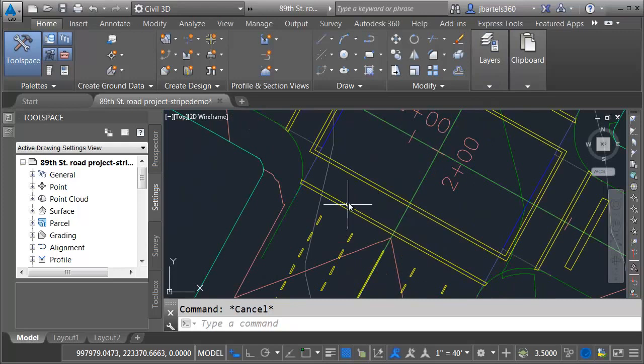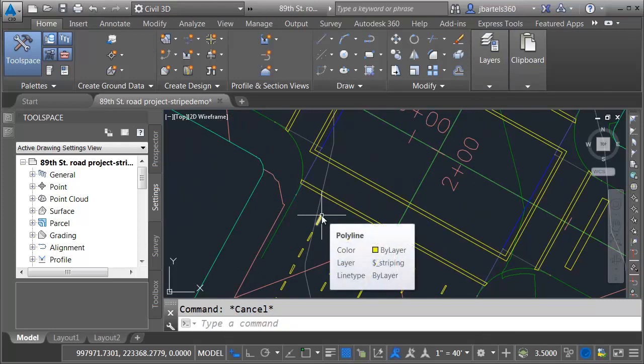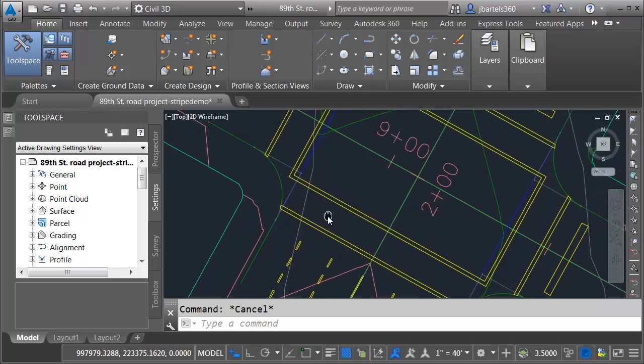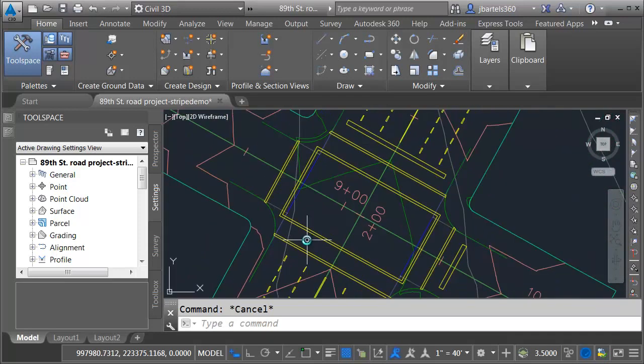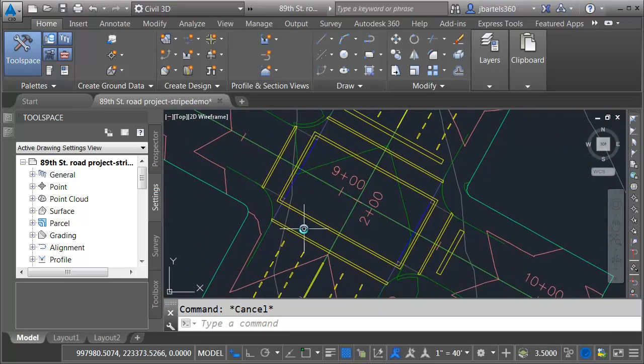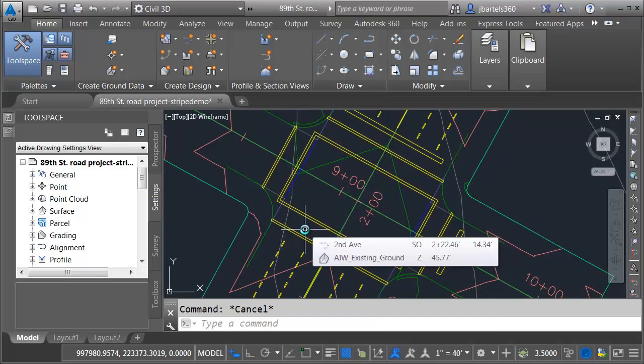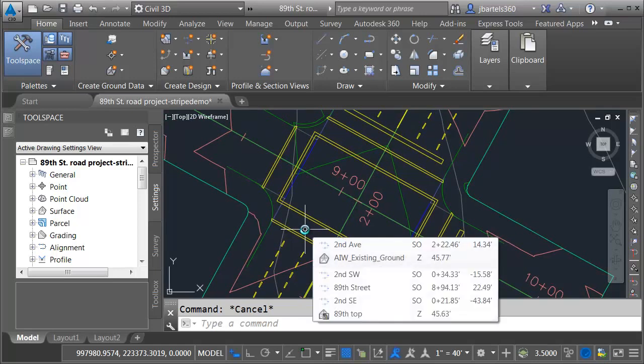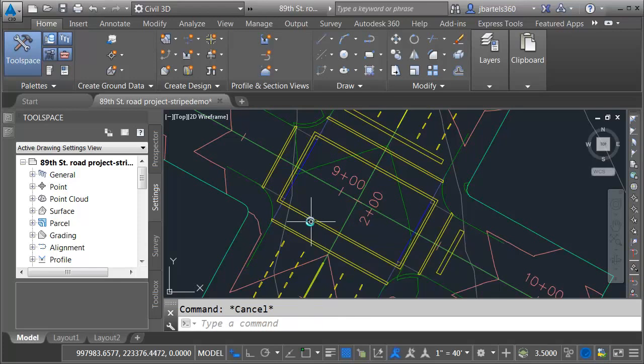If I zoom in, you can see the geometry that I've created. These are all polylines. They were created using traditional AutoCAD functionality, offset, fillet, commands like that. The first thing I'm going to do is convert these polylines into regions. Regions are considered solids, although they have no volume. They'll reflect light, though.